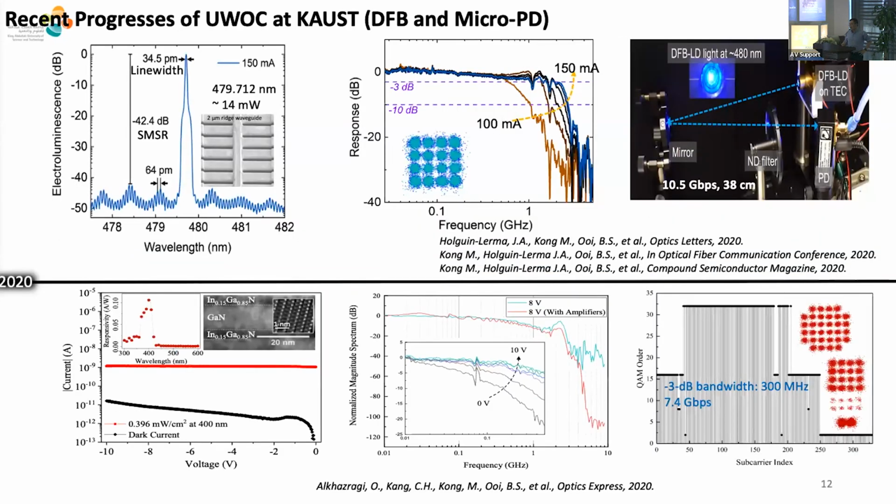There are a lot of missing components that we need to develop, because unlike the optical communications that people are using for our internet and underwater fiber optics, we do not have many things, especially a very high performance laser as a transmitter that you can modulate at very, very fast bit rates. So we make our own semiconductor laser. We make a very narrow bandwidth, very narrow linewidth laser, so that we'll be able to push a single laser up to 10 gigabit per second.